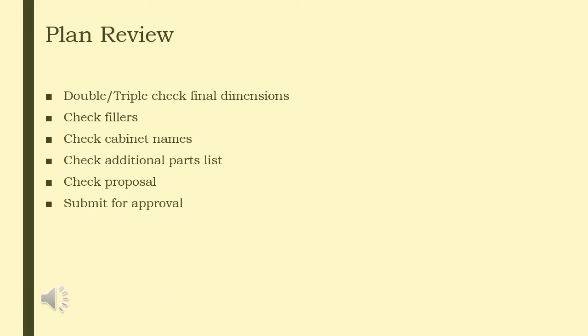Plan review was the last step before taking the layouts to become submittals, which are the layouts that are submitted to the client for review. My checklist was that I would triple check the dimensions and even had my boss check a few that were vague and within the plans. I checked that I followed overlay rules and that the proper fillers were used, and checked the cabinet names to ensure that the product list would be correct.